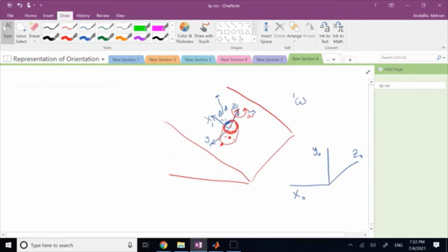The gyros are going to give you 3 angular velocities, and these 3 angular velocities are definitely measured with respect to a frame attached to the airplane. But the airplane has gone through lots of different rotations: roll, pitch, yaw. Now if it wants to report its angular velocities to the base, or the base is trying to simulate its motion or find out where it is going, they definitely need to project everything along their own inertial system.